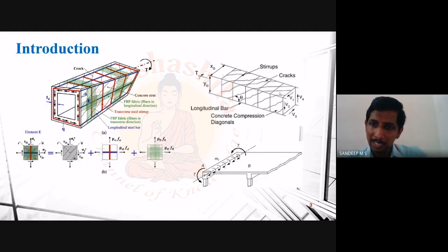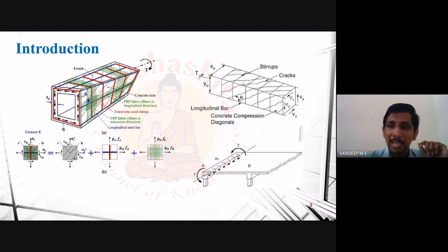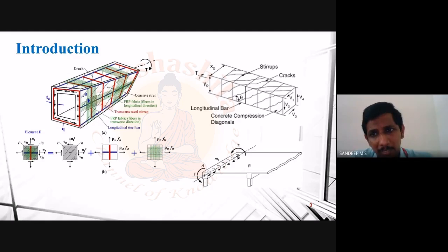So what I want to tell you is that once a beam is subjected to torsion, the formation of cracks will be like this. It will be almost at an angle of 45 degrees, as shown in this figure. Normally this angle will be approximately 45 degrees. We have seen cracks forming at approximately 45 degrees somewhere else. Where was it? Do you remember? Please tell me.